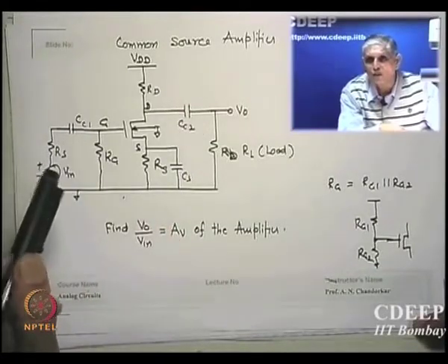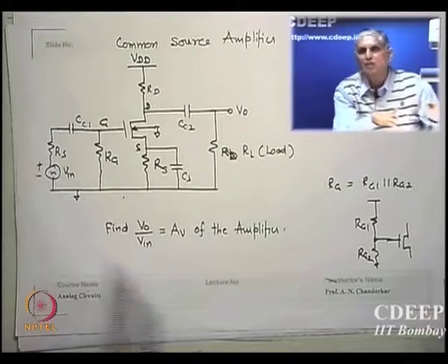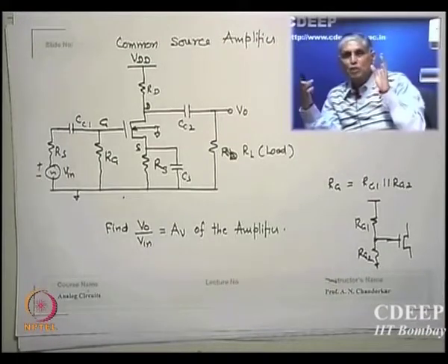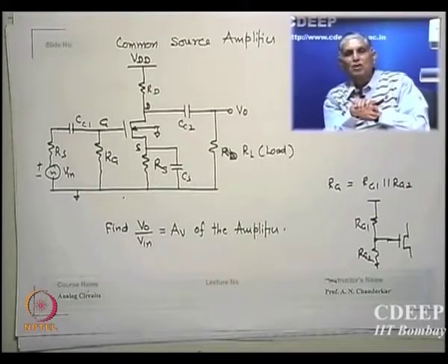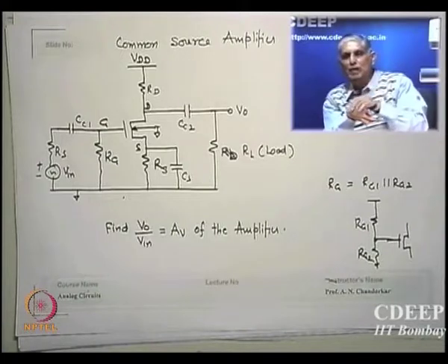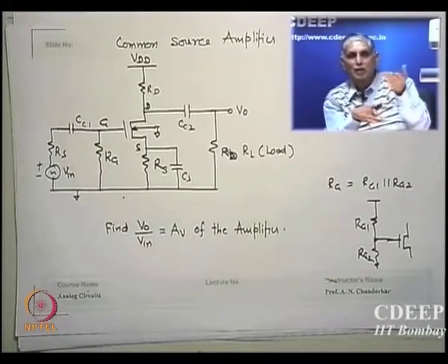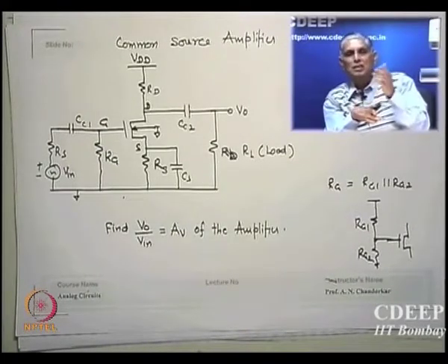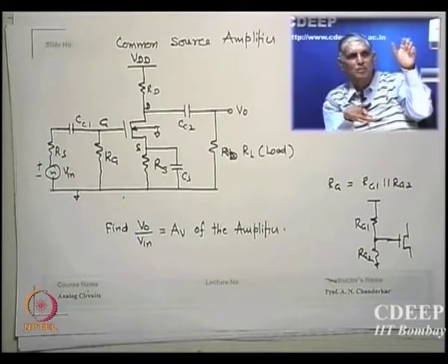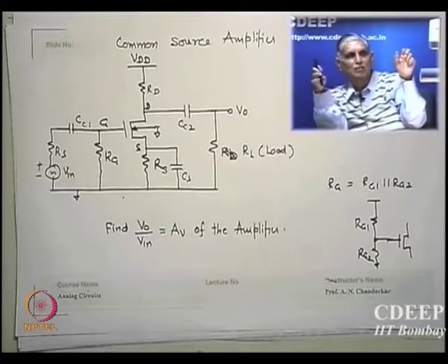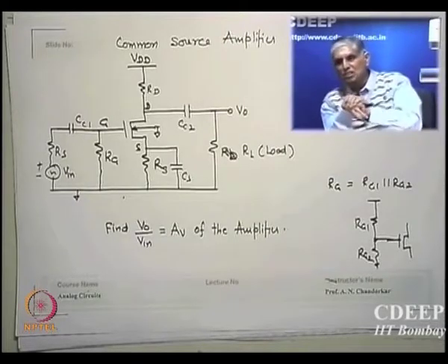Practically 0. So what should be the values of them, because omega is not going to be very high, we are going to use smaller frequencies as of now. So C should be very high, typically some microfarads, 0.47 microfarads or 1 microfarad could be the decoupling capacitors. In some experiment you may be doing, you can think why we are putting a larger value of C in the series connections.